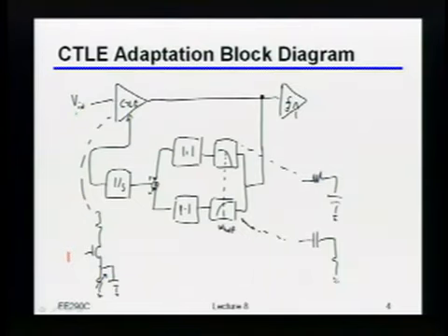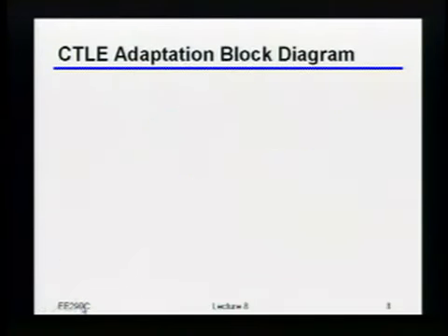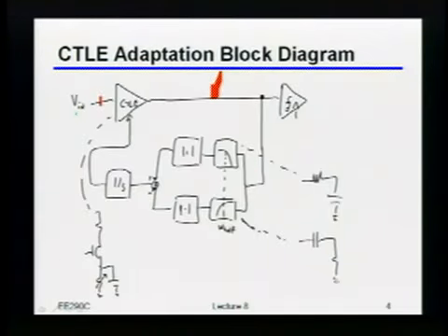Oh, okay. So in reality, even this filter will end up being band pass. Although, remember, what's coming out of here actually has the low pass behavior, right? Because my CTLE already has finite bandwidth. So in other words, if I looked at the transfer function from this point to this point, it would actually be band pass. Right? So I'm relying on the bandwidth of the CTLE to naturally set the other half of that band pass filter.